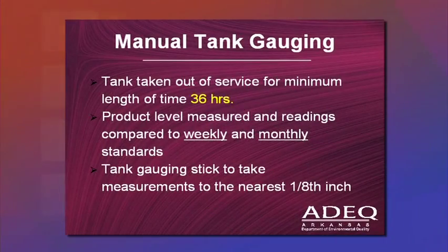The product level has to be measured and the readings have to be compared to both weekly and monthly standards. So again, manual tank gauging, you're doing inventory control, you're taking stick measurements to the nearest 1/8 of an inch in the tanks.